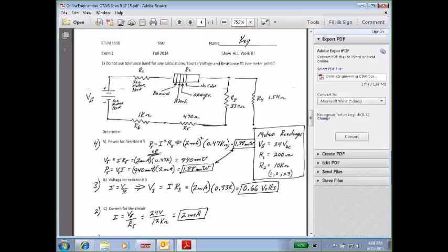And with that, I point out that the larger the gauge number of the wire, the smaller physically the wire is getting, which means that if the wire is getting smaller in diameter, then the resistance of it is getting greater as we go along that wire table. So those are all background information that I would have covered before they would get to an exam like this, obviously.